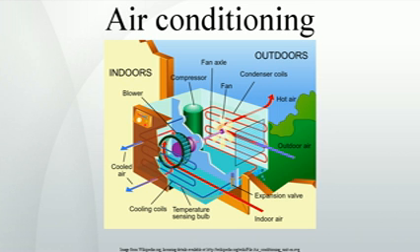Having the condenser coil in the same air path as the evaporator coil produces warm, dehumidified air. The evaporator, cold, coil is placed first in the air path, dehumidifying the air exactly as a regular air conditioner does. The air next passes over the condenser coil, rewarming the now dehumidified air. Having the condenser coil in the main air path rather than in a separate, outdoor air path, as with a regular air conditioner, results in two consequences: the output air is warm rather than cold, and the unit is able to be placed anywhere in the environment to be conditioned, without a need to have the condenser outdoors.